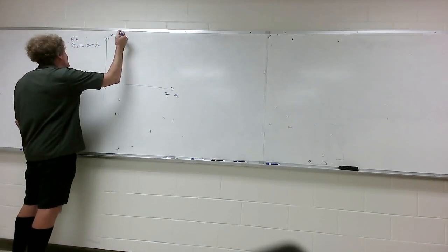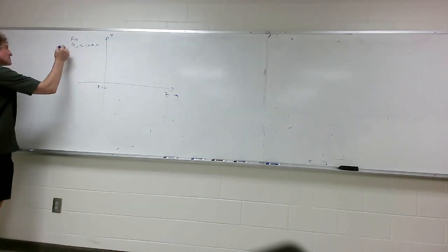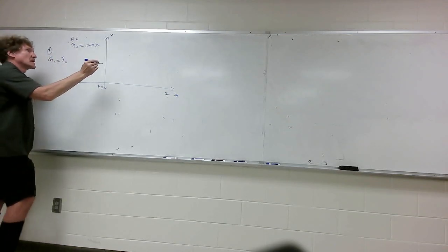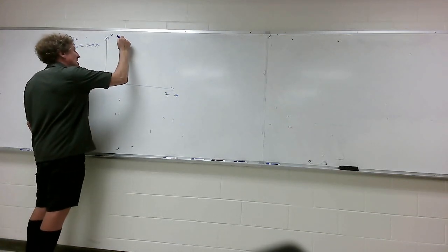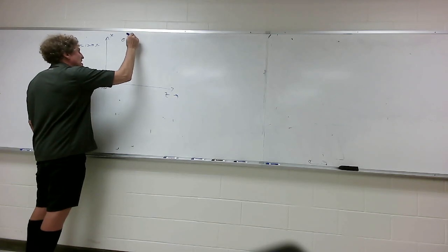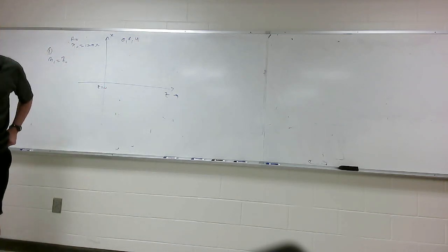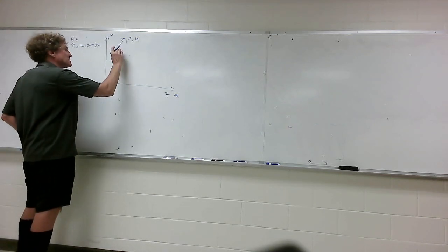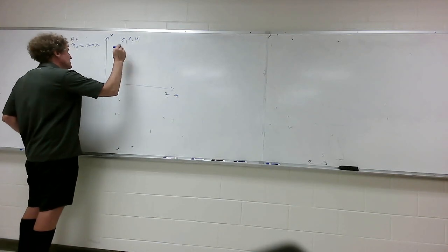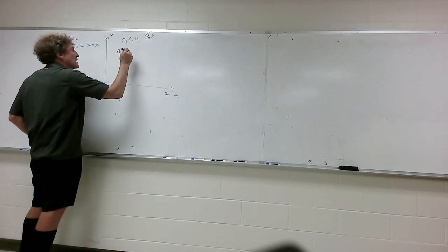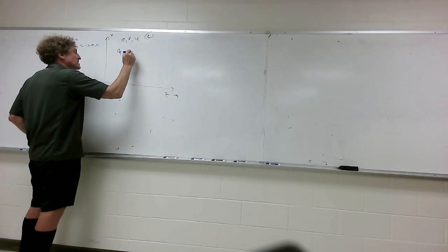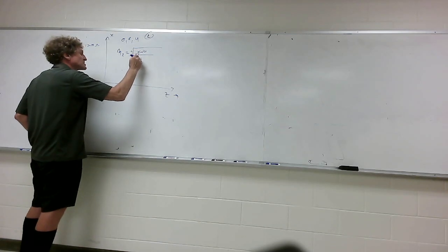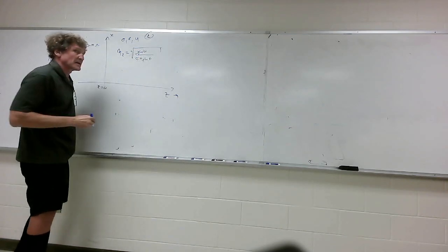Now this material here is going to be material 2. There's going to be a different material. As a matter of fact, I'll call this region 1. So in region 1, the intrinsic impedance is eta naught. And in region 2, it could have a sigma, an epsilon, a mu that aren't equal to free space values. Y'all with me? That means this region will have a different intrinsic impedance. So this is media 2, and the intrinsic impedance of this media will be equal to the square root of j omega mu over sigma plus j omega epsilon.